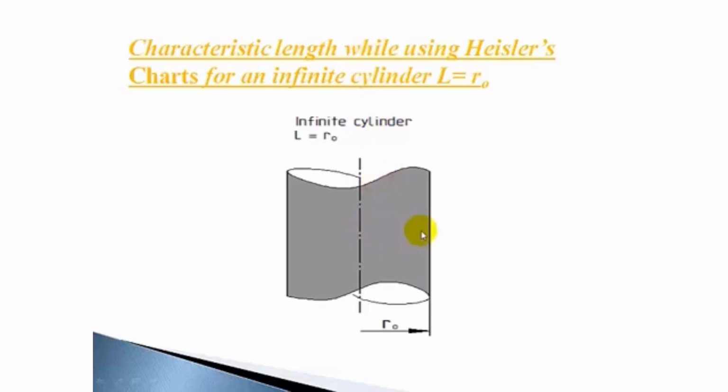So when it is an infinite cylinder or a very long cylinder, the conduction will be in one direction. And it is an unsteady state process. The temperature is varying with respect to time, and also with respect to distance, but only in the radial direction. Initially, at any radius you take, the temperature is the initial temperature, Ti. But later on, the surface will cool fast, whereas the axis will remain at a higher temperature. So there will be a difference in temperature between axis and surface, a variation in temperature from axis to surface. With respect to the radius, we can find out the temperature.